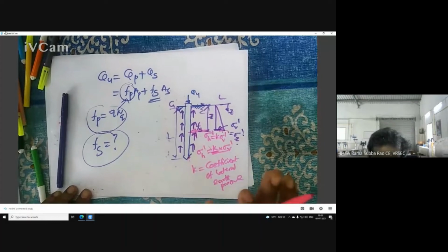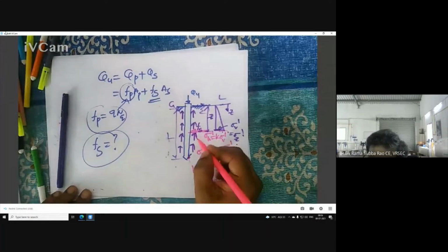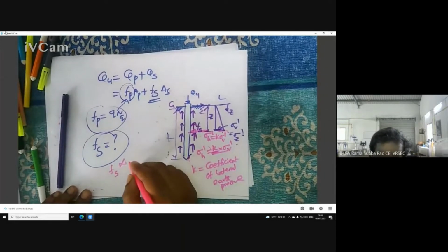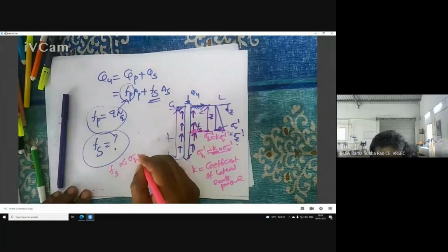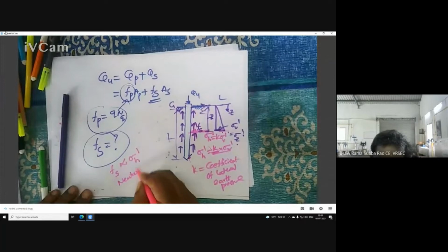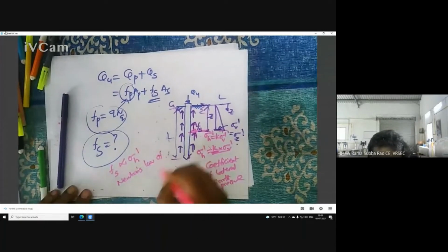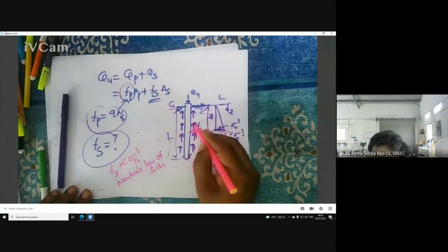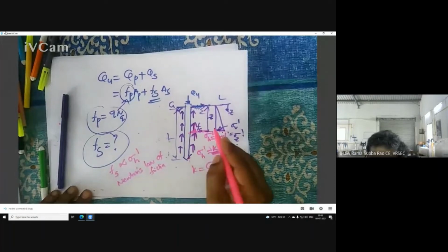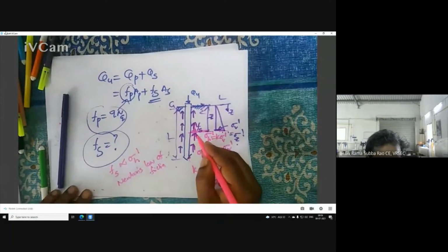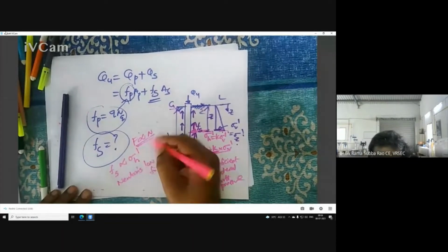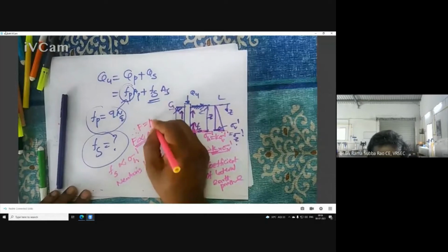Now what I'm trying to tell you, now I want to transfer this as a skin friction. Fs is directly proportional to sigma H dash. Now what I'm trying to tell you, this is Newton's law of friction. I have a normal force, that is skin friction. So Fs is directly proportional to my sigma H dash. So F is directly proportional to N. Can anyone answer now? How to calculate F now? F is equal to mu into N.